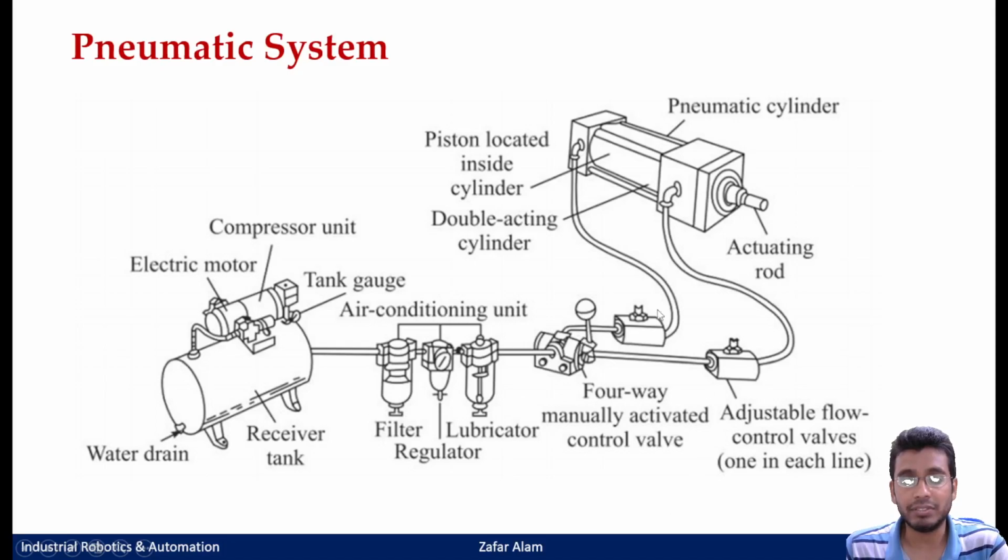Okay, this valve, if you see here, is a manually controlled valve. A valve was also required in your hydraulic circuit. And then finally this is a cylinder. So again, if you pump the pressurized or compressed air through this unit, then the cylinder would extend. And if you have to retract the cylinder, then you would put the pressurized air from this port, and it would retract the cylinder.